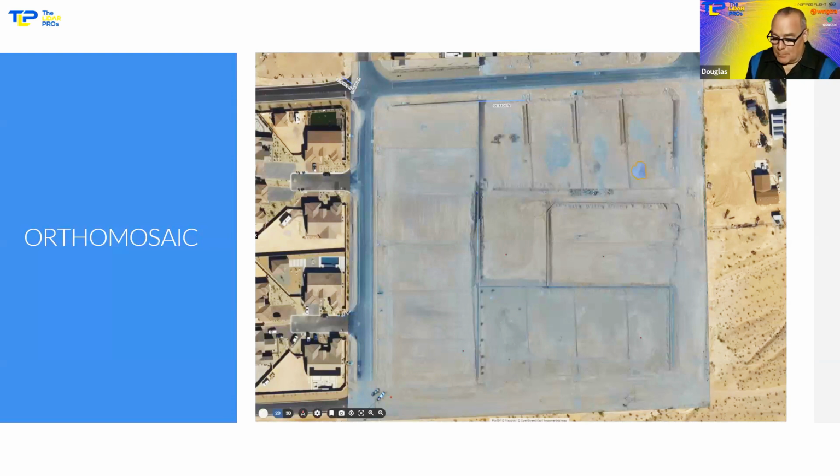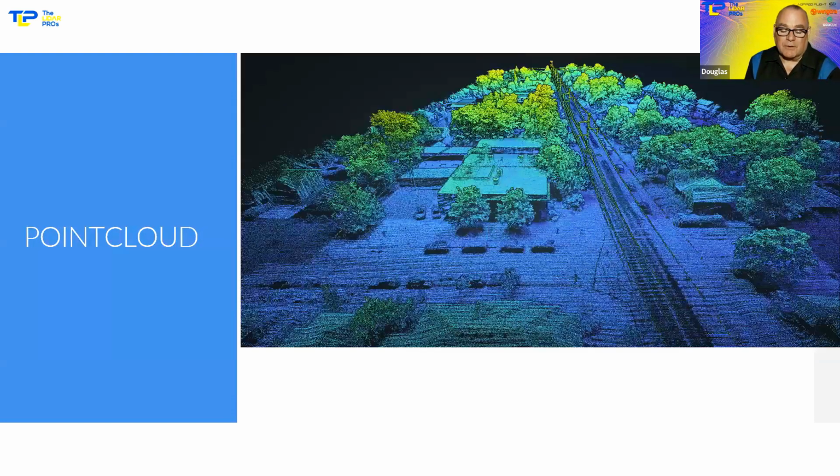So to develop a point cloud similar to the one that you see here, we're going to run that flight through. And in this particular case, this is about a 5 to 7 minute flight. The processing of this data to see it in its raw form is going to be between 5 and 10 minutes at most. And then we can start cleaning that point cloud if we need to. If we don't need to clean the point cloud, we can feed this into our AI software that's going to discover or look into our encroachments, and it will deliver that encroachment report in under 5 minutes.